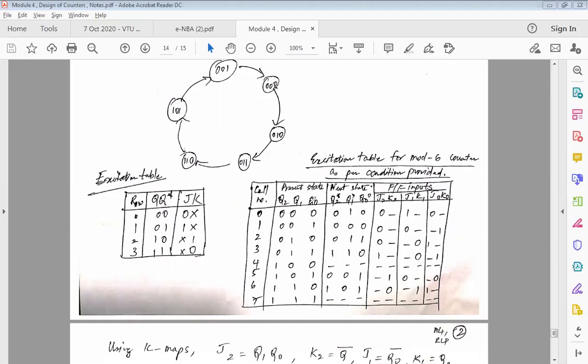Sir, I had a doubt in the fourth state, where the inputs are 100. Why is it a dash, sir? There is no next state for that input. I've already explained this. Can you find 100 here? Is there a 100? No. So I do not know what state is going to happen, so I'm giving a don't care, which means that state you don't consider at all. I'm telling my circuit not to consider 100 because I do not have it in my question. I have to use only those which are in my question.